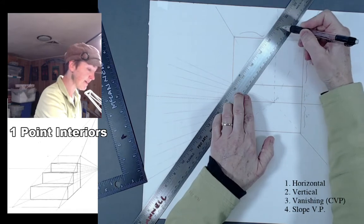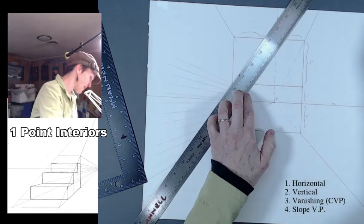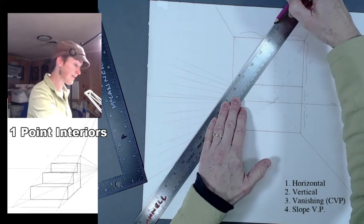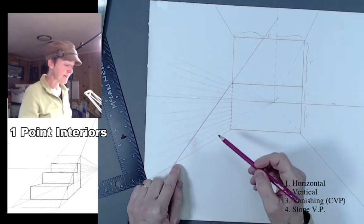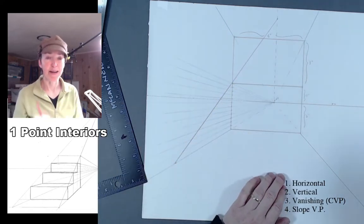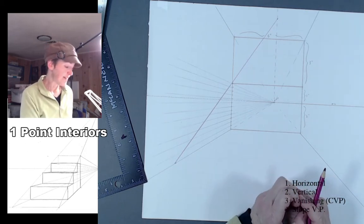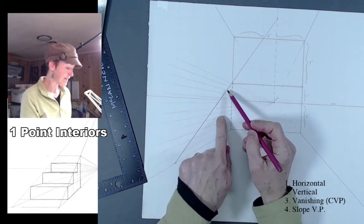So we're going to find a point here. And I'm going to draw this with a different color just so that we can keep it straight from our other. So this is a pink, like magenta color pencil. And that's going to be the slope that we're following when we're plotting out the steps. We're going to be adding another one later, like is showing in this slide right below my video. But we first need to decide how wide we want the steps to be. So for now, we're just going to be plotting out what the profile of the steps looks like.